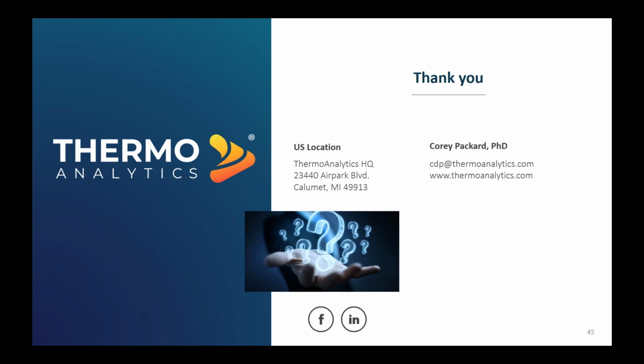MuSES can do that for you, so that what you see is a lower resolution image, where it's calculating that higher resolution image and averaging those subpixels together to get the physically accurate pixel values. You can set it up to do that. And of course, if you wanted to include other effects like atmospheric turbulence, depending on your viewing scenario, there's a variety of ways you can deal with that too. So yeah, good question.